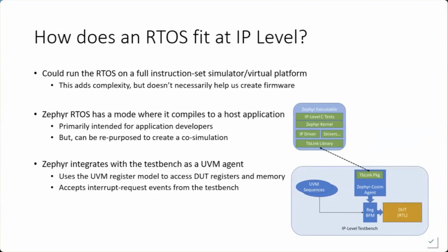There's a bit of a framework, some open source components, including a UVM agent that connects up to the register model to use the register model as a way to access the device registers, and then also provides services for channeling interrupts back up to the software behavior represented by the Zephyr executable.